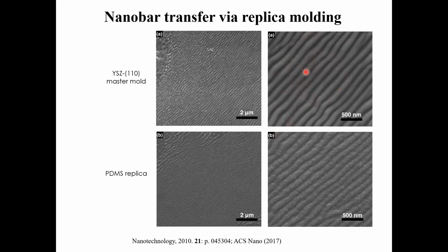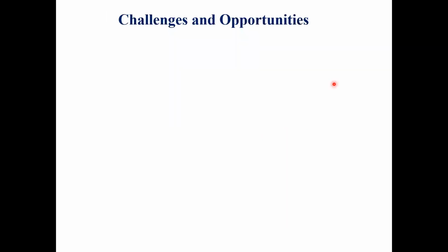So you can now study the anisotropic properties of your polymer, viscoelastic properties, mechanical behavior. Now that the spaghetti is aligned and ordered, it's going to have an impact on mechanical properties as well as electronic properties, like if you are doing this using electronic polymers.